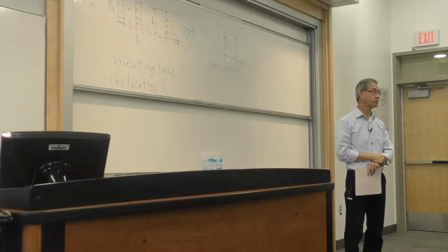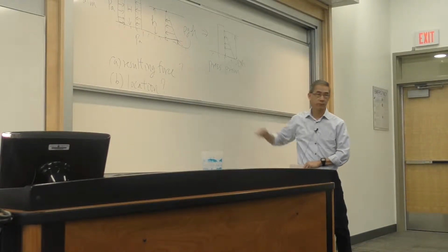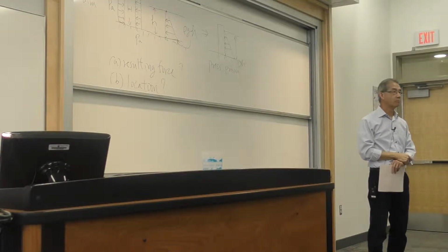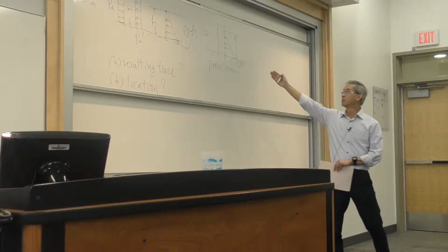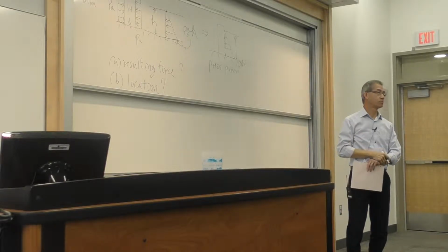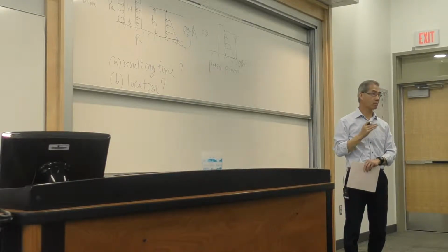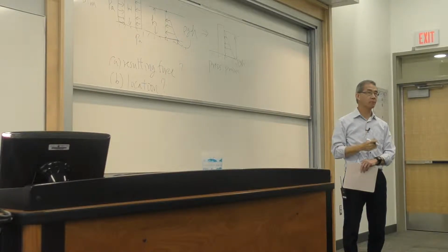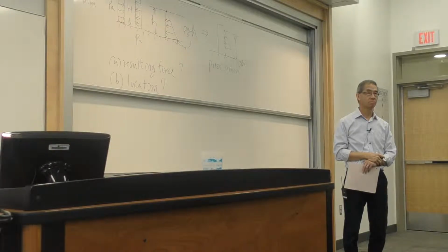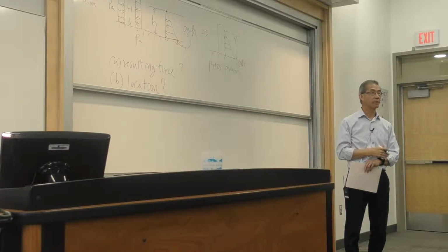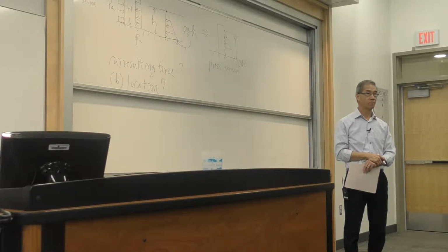This has now become your static problem. Forget about the word fluid. Once I come to this point, we are done with water. You now have just a pressure or loading distribution that is non-linear, non-uniform. Zero at one point, rho gh at another point. From that, based on your statics, tell me what is the resultant force and where is the line of action, the center of pressure. Remember all that from your statics? Okay? Are you ready for that?